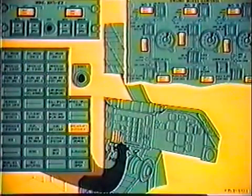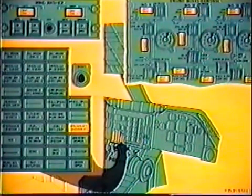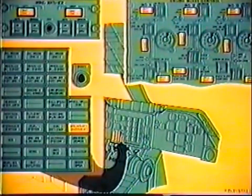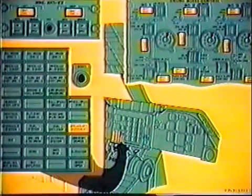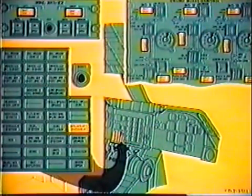The area overheat detection system is tested by a 3-position selector and a push-button test switch. When tested, all 7 area overheat lights on the pneumatic and air conditioning panel illuminate. The 2 wing anti-ice duct fail lights on the overhead switch panel will also illuminate. The area duct overheat light on the pilot's annunciator panel will illuminate anytime an area overheat or duct overheat light on the second officer's panel illuminates. It is also illuminated with the area overheat test.